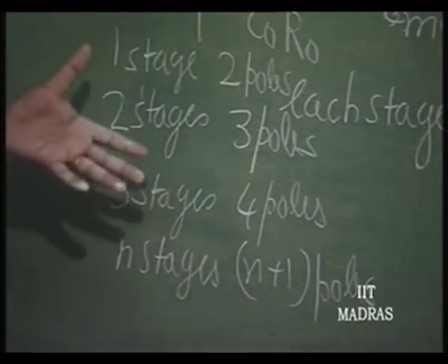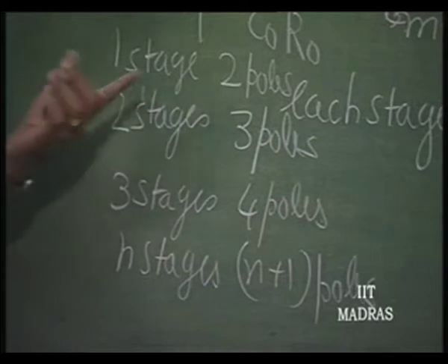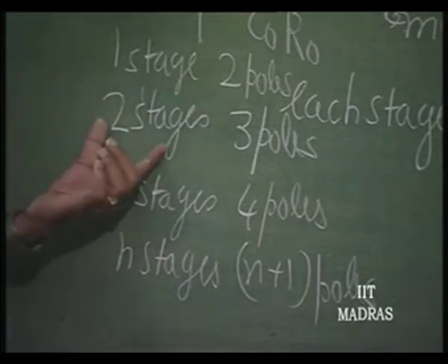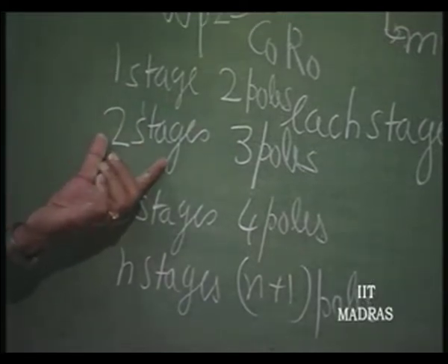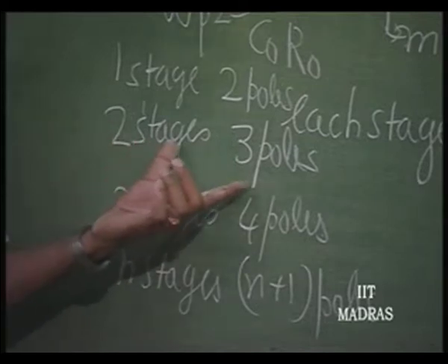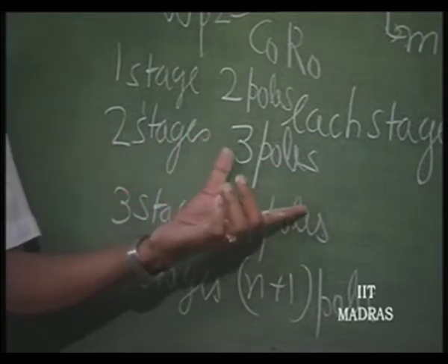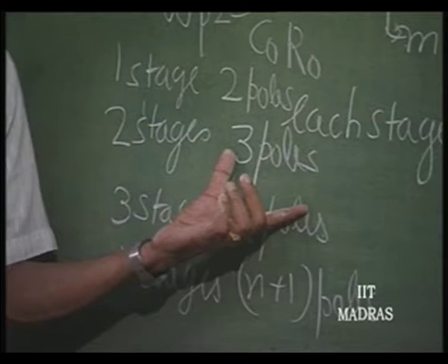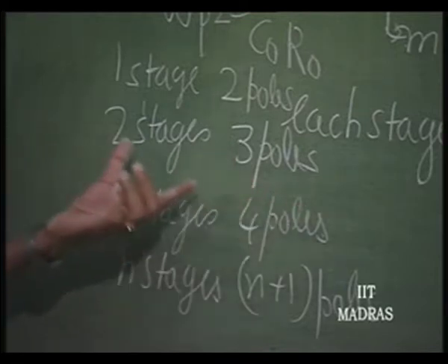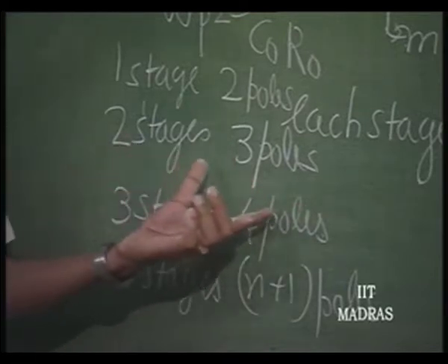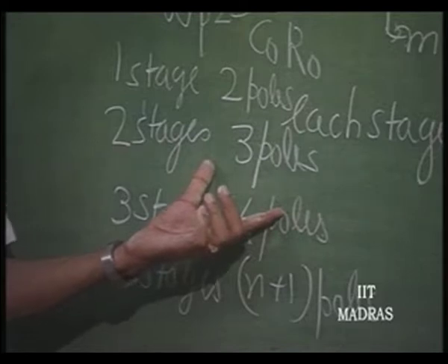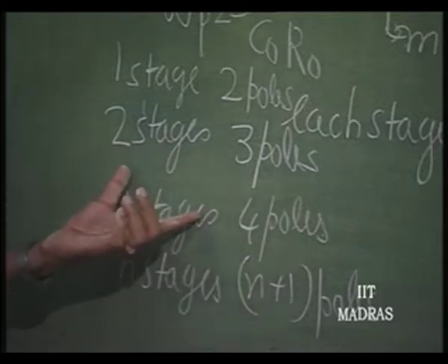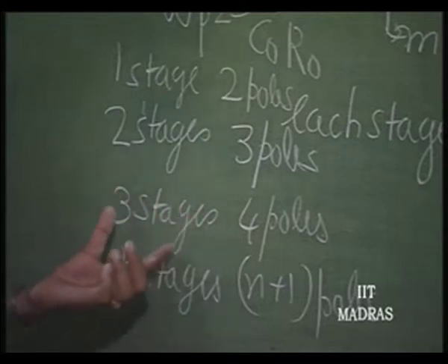And therefore, we have already seen that we will get into problem most probably when we connect 2 stages, because it will result in 3 poles, and most probably the frequency compensation may become necessary here, cutting down on the bandwidth maybe, if the loop gain is high. So, definitely in 3 stages.